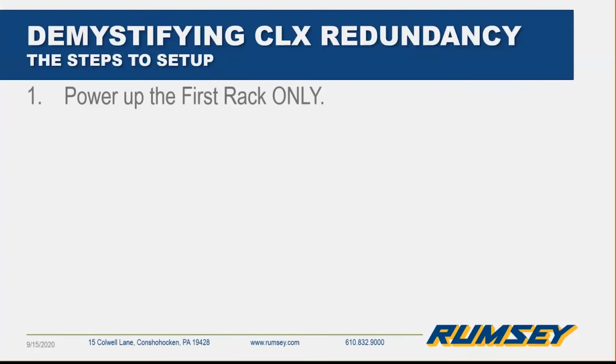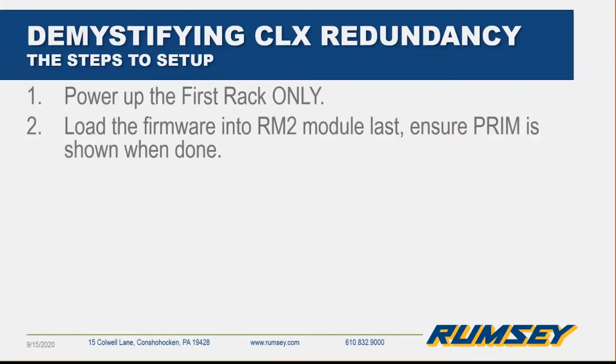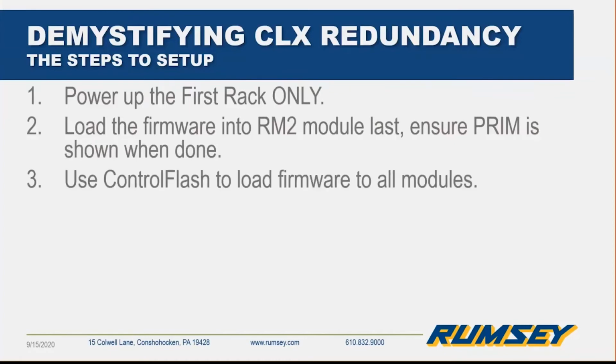Now, this is just the first rack we're talking about for the pair of hosts. I put this first, even though you do it last. You're going to load the firmware into the RM2 module last. But I want to tell you now, because if you start grabbing things and going to the next step, you might get yourself into something you'd have to fool around with to get it to sync up. So again, do ControlFLASH, do all the modules except the RM2, which goes last.